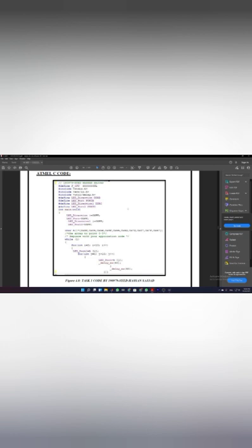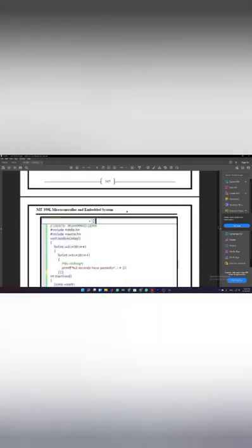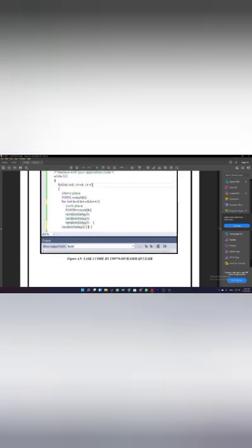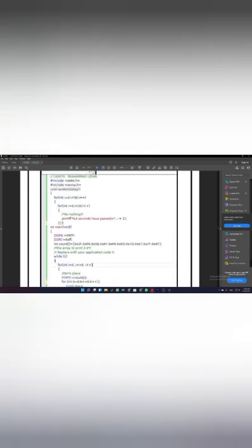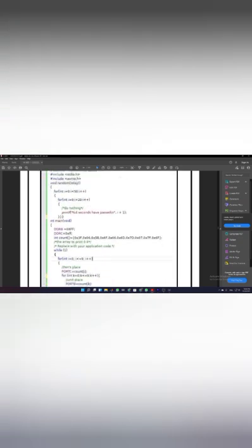You can see that we have defined the CPU and the LED directions, DDRB. These are the standard libraries that we are defining here, and then in the main void function we will see that the LED direction will be the output, 0xFF, and LED port 0 means all the outputs are declared as outputs. Then we will use the two-dimensional for loops in order to print to the LCD at port A with a delay of 50 milliseconds.